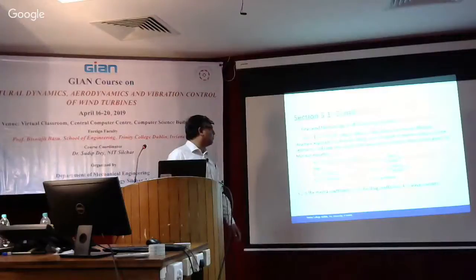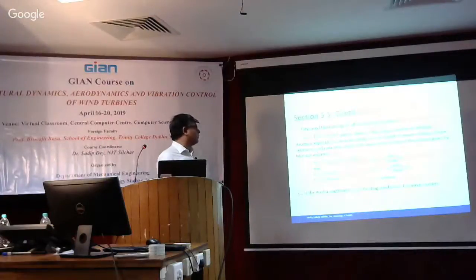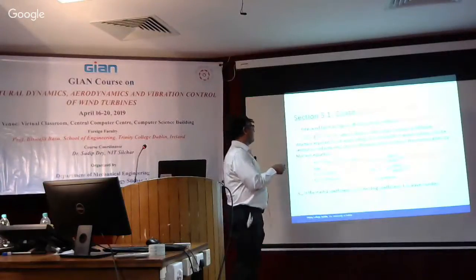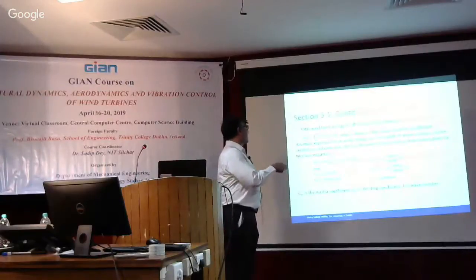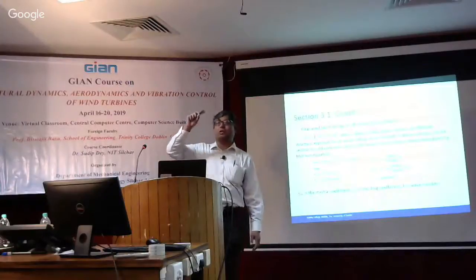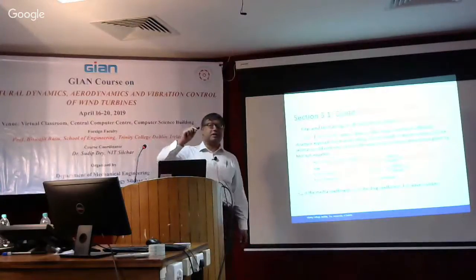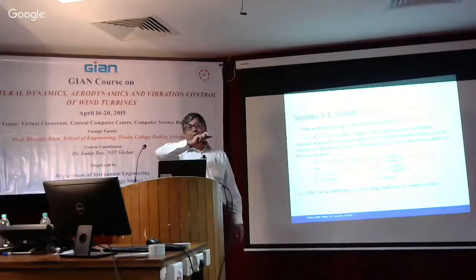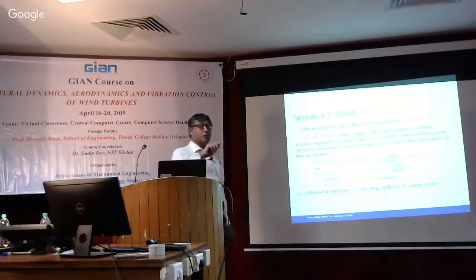The total wind force acting on an offshore wind turbine can be obtained by calculating the wind pressure acting on the blade or on the tower, or for the spar it has to be the hydrodynamic load. Then you apply the shape function, which is the mode shape, and you get the modal load as we did previously. In the structural dynamic model, I showed you the generalized load, which included the distributed force and the mode shapes.